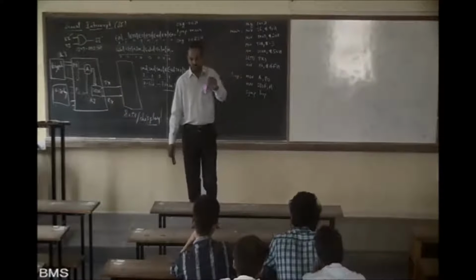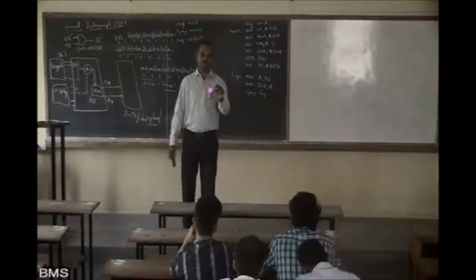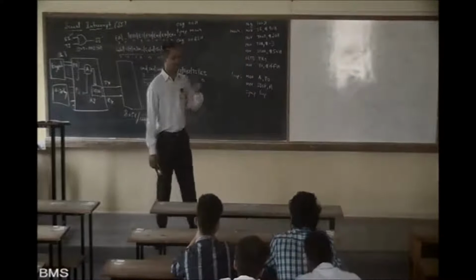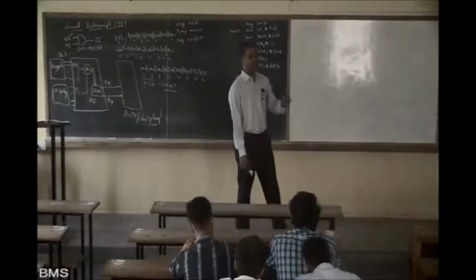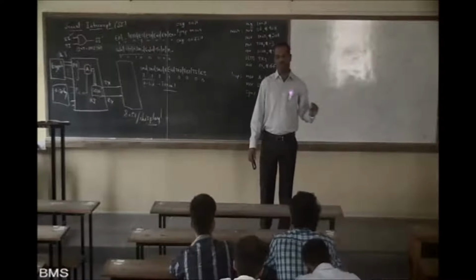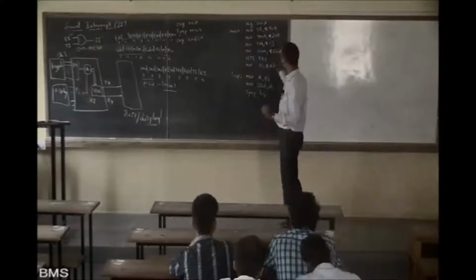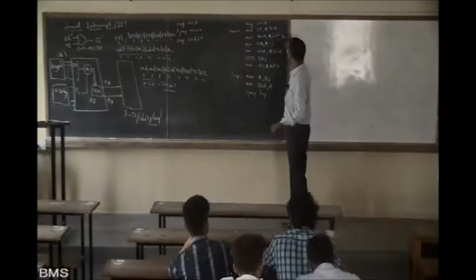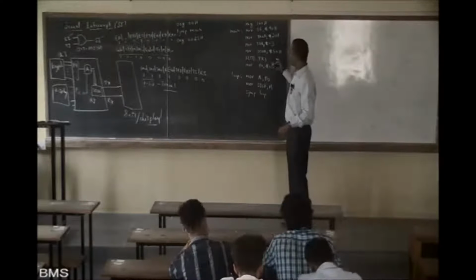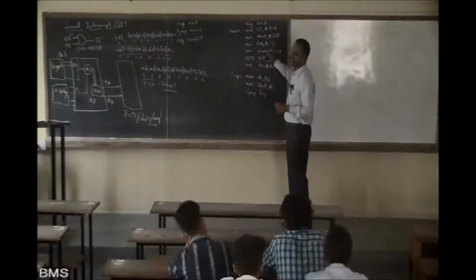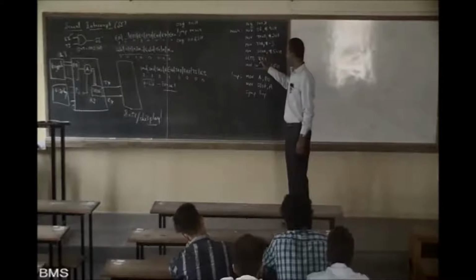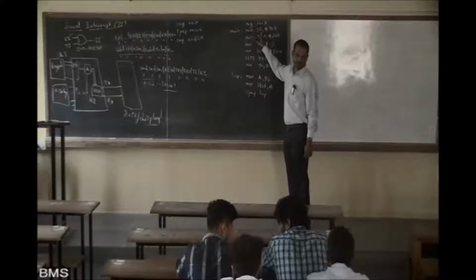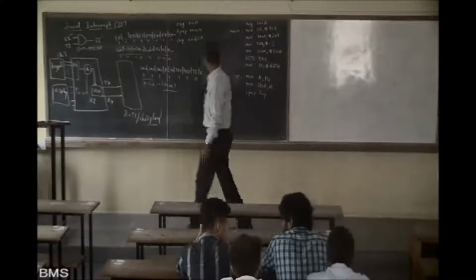If you are working on serial communication, the first thing that should come to your mind is to set the SCON register. If you are working on the timer, the first thing that should come to your mind is to set TMOD and TCON. Similarly, once you set SCON, you should know what you are setting. It should actually be SCON first, then TMOD, then TH0, then TH1. Then if you are working on interrupts, then this one. Clear? Right, next.